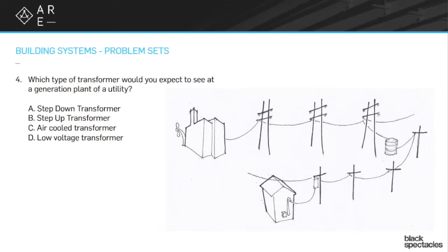It depends on how close you are to the power generation. There's a whole series of different issues that are going to happen on here. But the gist of it is you're going to step up for the big distances. You're going to step down for distribution, and then you're going to step down again for actual use.